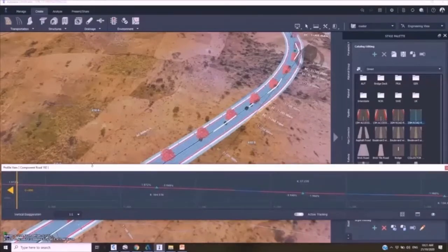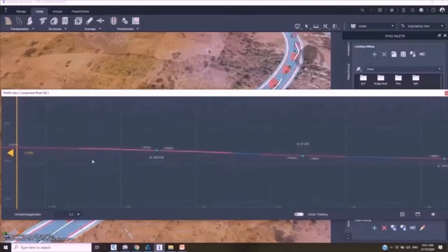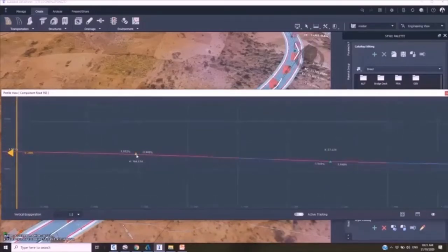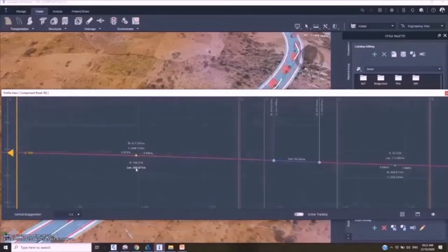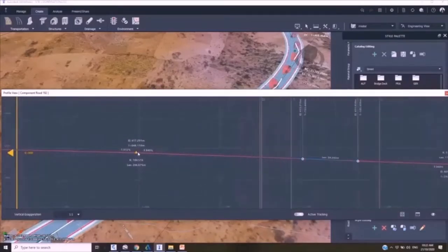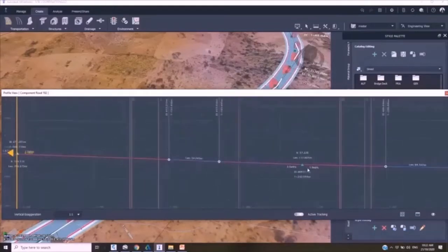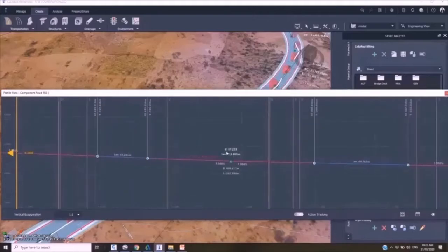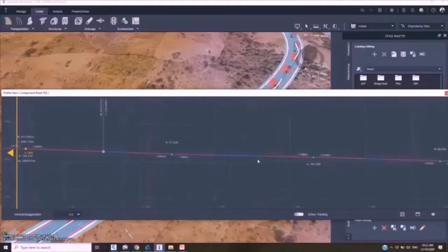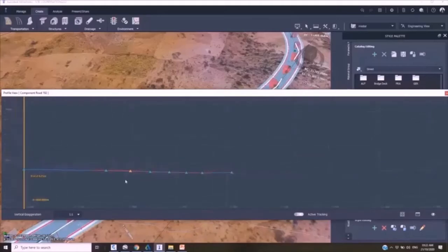Now what I'm seeing here is the profile view of the locations. At this level, I can do my adjustment with respect to details that reflect either my K value descriptions pertaining to this road. So these are the levels where all design criteria will be considered for the vertical profiling. Kindly note that design speed determines all other conditions that will define the horizontal profile and the vertical extent. So at this level, you can adjust, apply, edit, and consider the design criteria being shown for this road by adjusting all these details to reflect what you actually want.